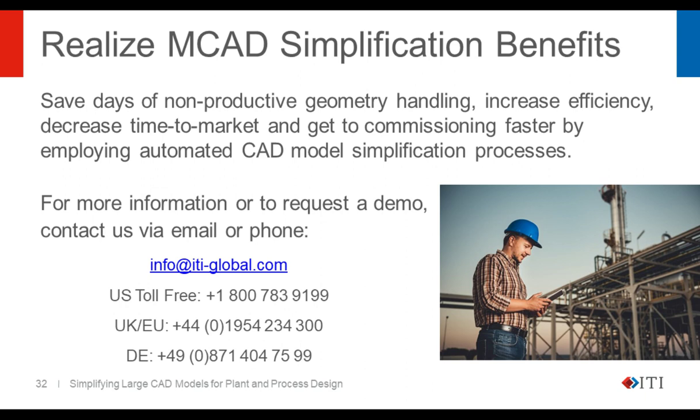Great. We have some great questions here. Another great one's coming up here, asks, will it support my workflow on Revit, considering the workflow of LODs? We don't. So our level of detail specification is controlled by the icons in the simplification wizard, the 3 levels of detail that we have there. And each of those 3 levels of detail has associated options and tolerances that the user can define. So whilst they're not explicitly linked to a particular Revit level of detail or workflow, they can be tuned by the user to match the settings they want.